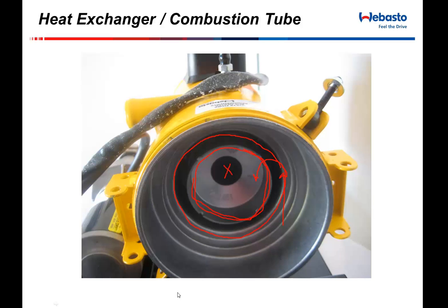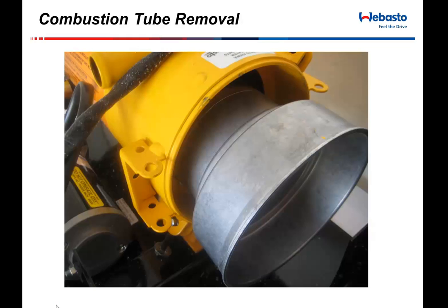You can pull this heat exchanger out, or this burner tube out, and I'm a big fan of if it's not broken, don't fix it. But any time that you do open up the burner head to the Webasto, get in the habit of pulling out this burner tube, and you may have to take a flat screwdriver and a mallet and give it a whack in here to separate the two.